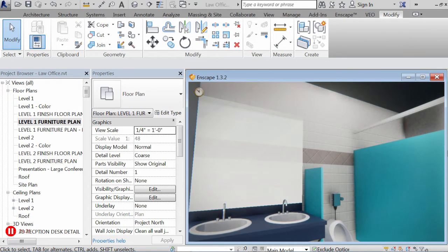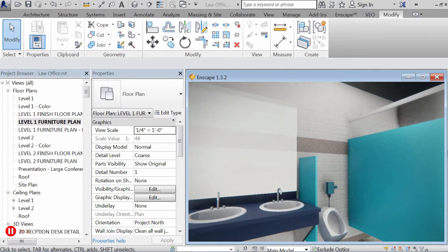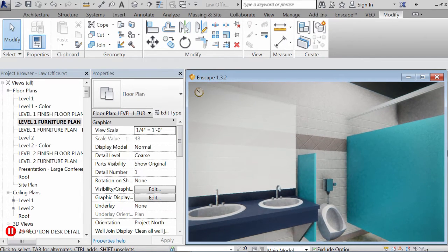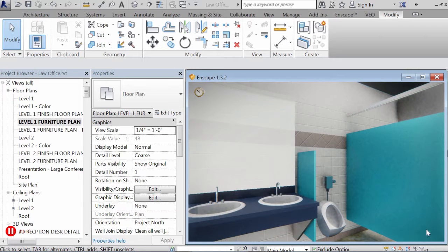You have to turn on the preview and set it to section, and then you have to cut the gypsum board to be able to apply multiple materials to that wall in section. So the materials you see here are a derivative of using the wall type, not somebody using the split face and paint tool. So you're talking about the regions above and below. You're putting in another material region for this tile. Okay, and down here as well.